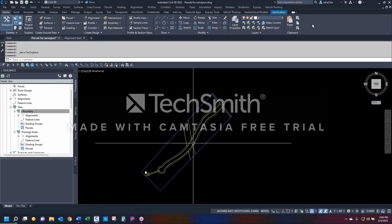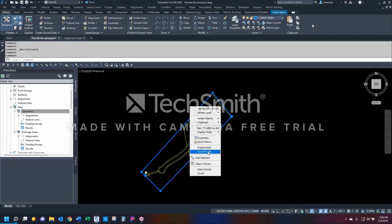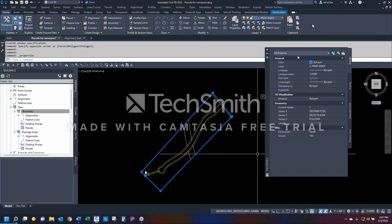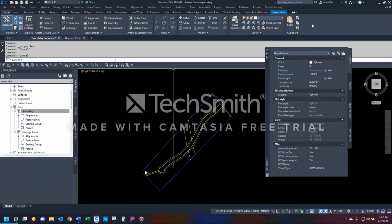I went through and spent some time, and I connected the dots with a polyline. Well, guess what that is? That's a polyline. So when I right click and it says polyline, hey, that's obvious. If I go into parcels, there you go. It's my three-dimensional polyline. I can flatten this, by the way. A 3D line can be flattened with Convert 3D Polys. That's the handwritten word for it; I don't know what button it is. You select your polyline, and yes, I do suggest doing this. Hit enter, and it converts it.